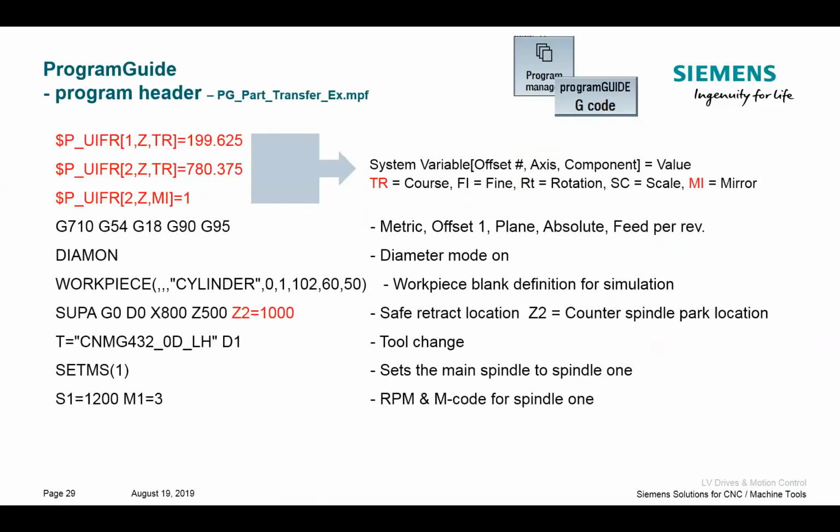So from there, it's time to start writing a part program. In the program, I have a couple new variables that you guys might not have seen before. We just calculated the G54 and the G55, right? That was done by the worksheet. So I could leave it up to the operator to type those numbers in.